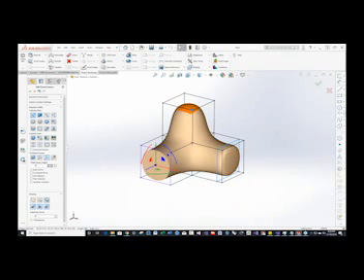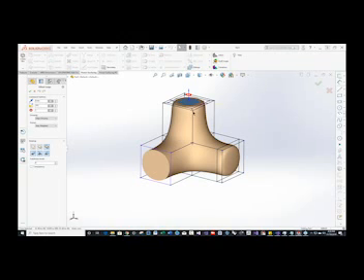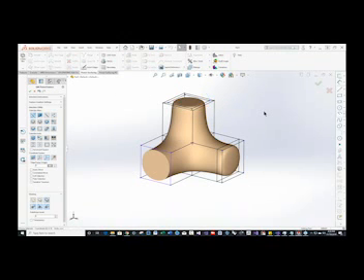I can do the same thing on the inside, where I do what's called an offset loop. And so I'm just going to offset this face, and so I've added a loop inside of that face. So you can see that there are different ways to do that sort of thing. If I double click on the middle of an edge, I'll select a ring, which is a ring around here. If I double click the end of an edge, we'll select a loop. So a ring is where the ends are not connected. A loop is a connected set of edges.